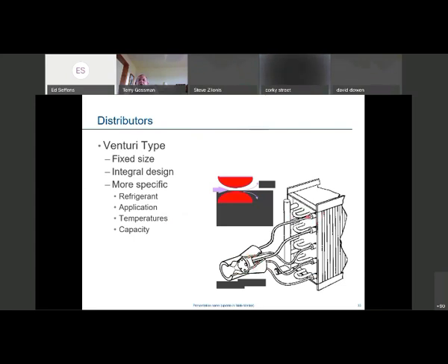Unfortunately, when we received a package unit with the evaporator and stuff, the manufacturer, now this never happens, right? The manufacturer sent us a system with the wrong distributor on it. So we actually had to change that distributor out. Now this is all one system too when sizing and selecting the expansion valve along with the distributor and the distributor tubes, right? The distributor tubes create a pressure drop as well, okay, along with this area right here.